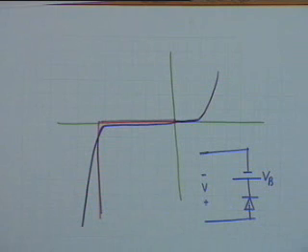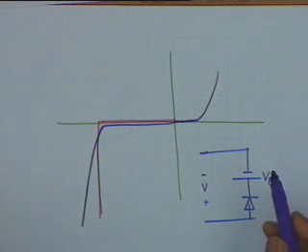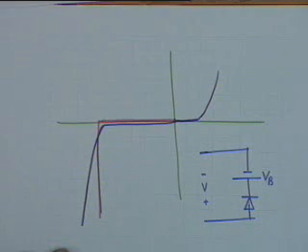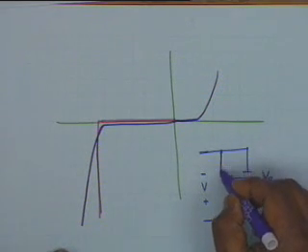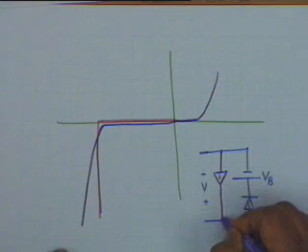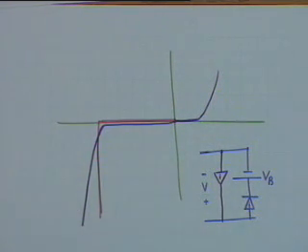All right, and after that, if it is the red curve, then we have approximated by an ideal diode. Now, in this, if you want to include its behavior as a normal diode, obviously you should put an ideal diode here, or an ideal diode in conjunction with a threshold voltage, RD, reverse saturation and all that. Now, since we are not using a Zener diode in the normal operation, we can forget about this. Is that clear? We are only considering the equivalent circuit when it is used in the Zener region or the Zener mode of operation.